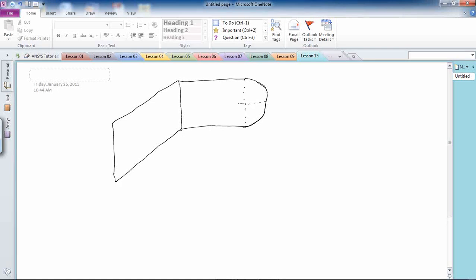And then right in this, concentric with this arc, I'm going to have another circle, which is going to be subtracted from the entire model. The thickness of this model is going to be 1 millimeter. This length is going to be 50 millimeters, and this one also up to here is going to be 50 millimeters. This length I'm going to give 40 millimeters.